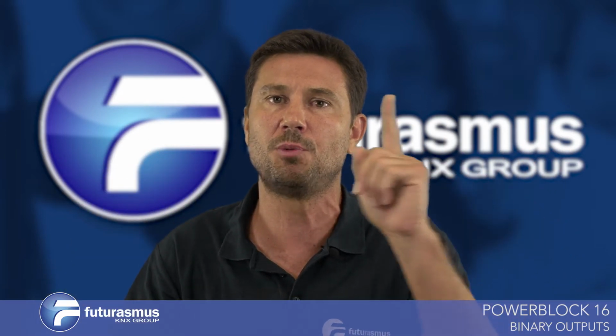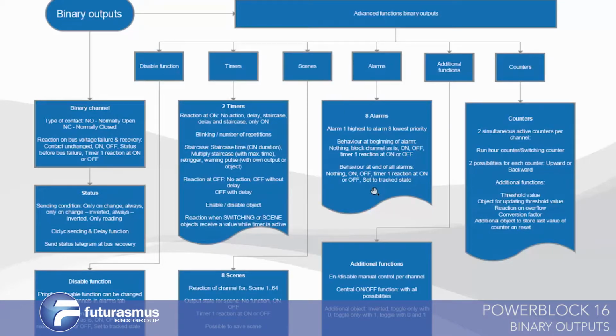Now, if you set it to the status before, there's a function called set to tracked state, then it will go to the on state, because the time switch switched it on at that time. So it will go to the state as if it was not blocked during that whole time. Okay, so this is very, very interesting also.